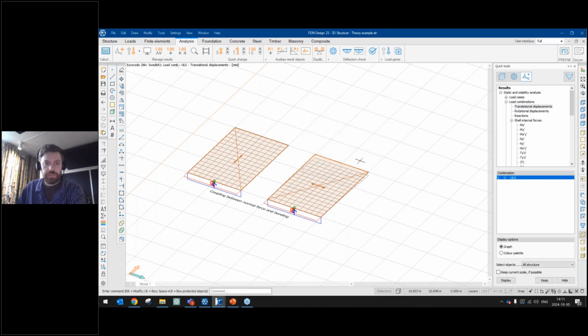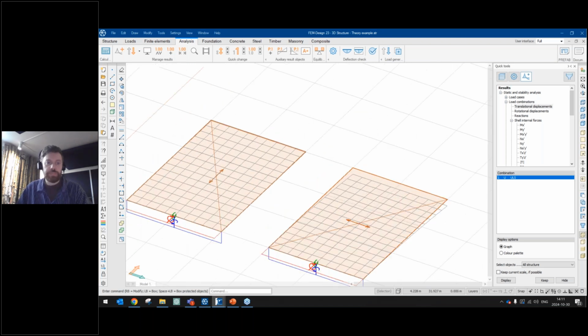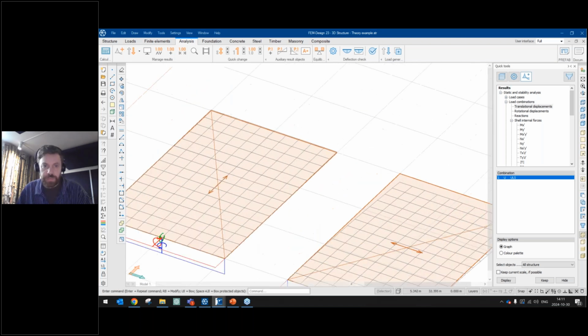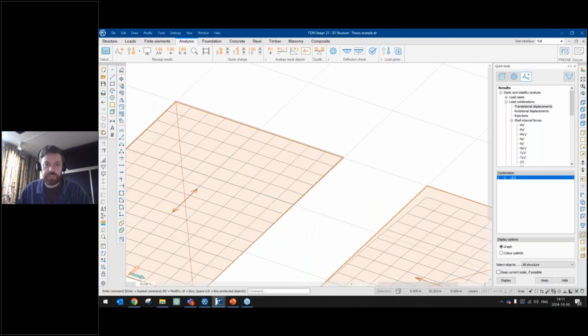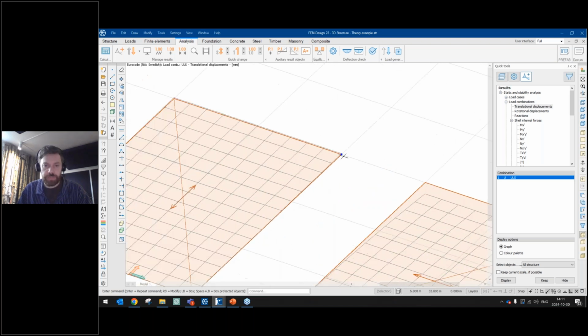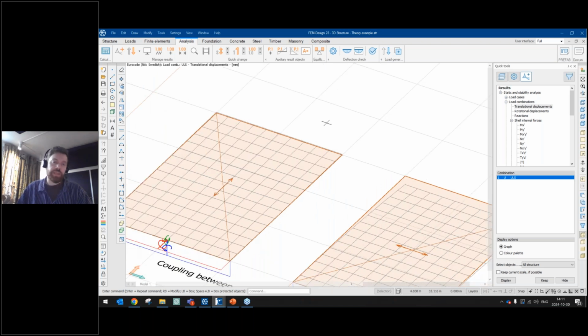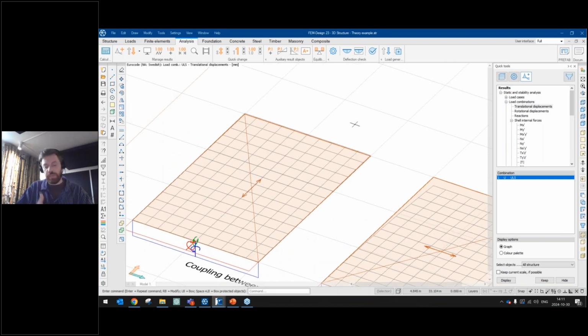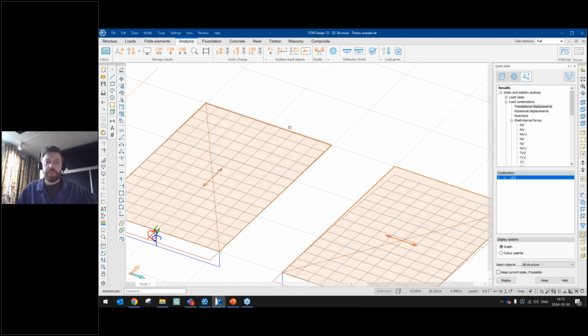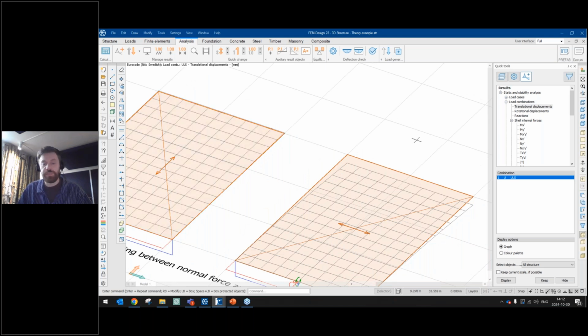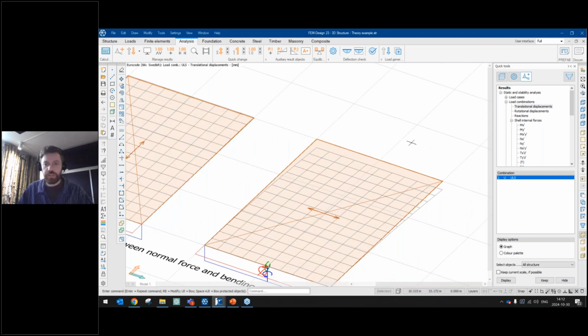All right. So when loaded in plane, I have a very small flexural stiffness bending deflection here. It's mainly just the connection between the main and perpendicular direction here that gives some forces in the, in this case, local y direction, which gives some bending. But the majority of the bending comes in the other direction because that's where it's asymmetric.